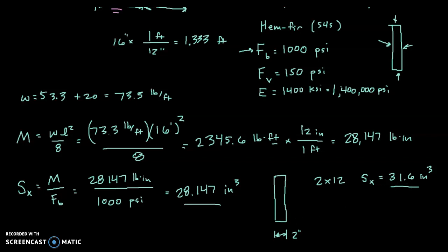Now we may need to take into consideration the self-weight. Occasionally the problem statement may tell you that you may neglect the self-weight, but if it doesn't specifically tell you that, then you should always take that into consideration. As I said before, wood has a pretty good strength-to-weight ratio, so the self-weight of timber usually doesn't make a big difference like it would in concrete, but it is something we should check nonetheless.